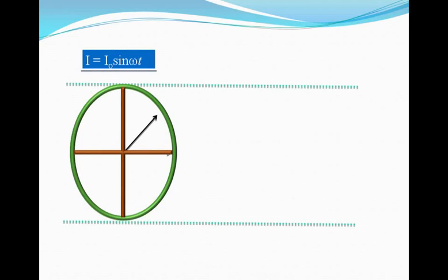So for example, here, as the electric current decreases, the phasor vector rotates, it becomes 0, the phasor vector keeps rotating, and here you can see that the phasor vector completes one rotation in exactly the same time as the electric current completes one cycle, isn't it? There you go. So basically what we've done is that we've represented the variation of electric current as a vector which keeps rotating, about a certain point.